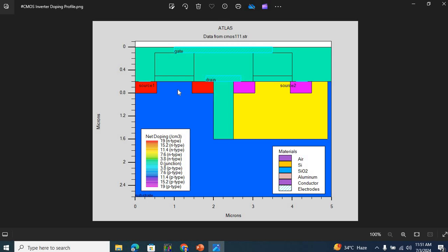So for the new generation, if I reduce each dimension and assume that this transistor is square in shape, and I reduce this side by 0.7 times and the inverse side as well by 0.7 times, 0.7 times 0.7 comes out to be 0.49, or approximately 0.5, which means that I have reduced the area of this transistor by approximately half.